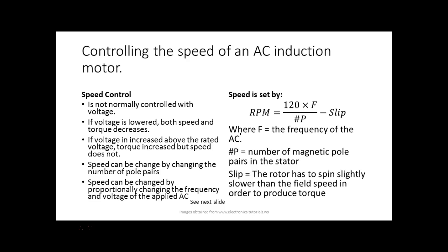That's why this motor right here is a three-speed motor, with all those wires coming out of it. The two brown ones are for your start capacitor, and then you have a red one, a yellow one, and a blue one. We're bringing power on each one of those to change the number of poles. If the number of poles goes up, the speed of the motor goes down.